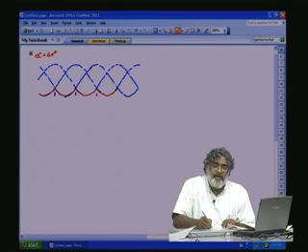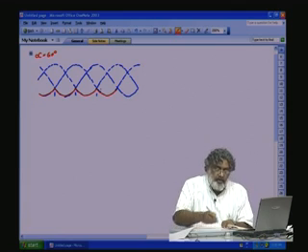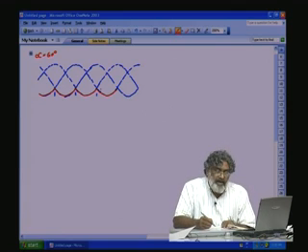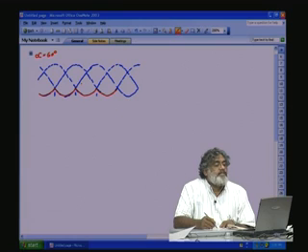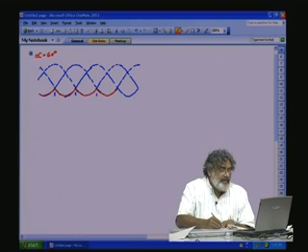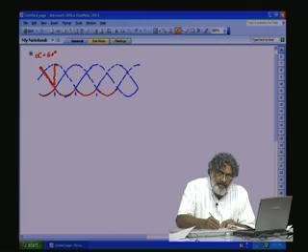Now, depending on the firing angle, the upper limb ripple will vary. In the present case we are studying alpha is equal to 60 degree. So 60 degree means it will be like this. See, this is the 60 degree from here to here, then from here it will immediately go here this way.